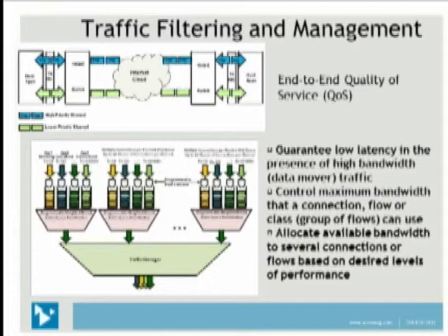And control applications require that you have a certain overall time period within which you want to get an answer, a little more of a deterministic requirement. So using some of the features on this card, you have the ability to configure certain ports to make sure that higher priority communications are recognized as higher priority communications, and you can perform some level of control over Ethernet.